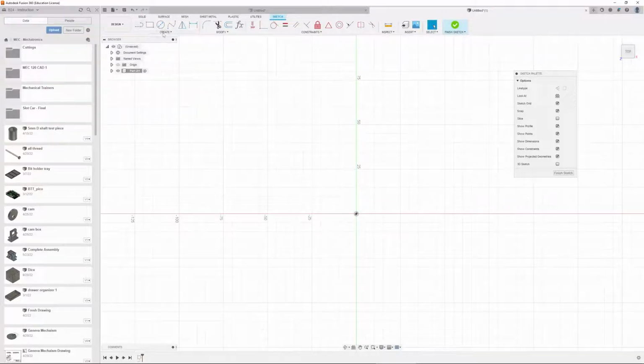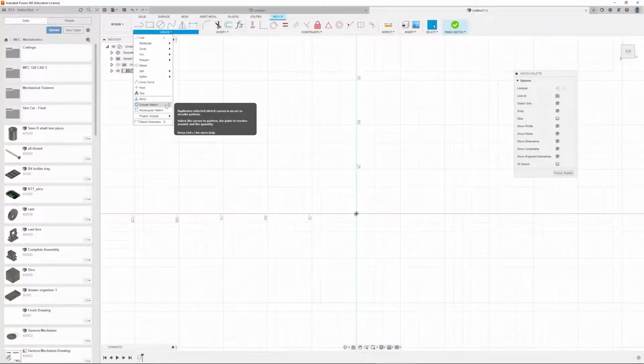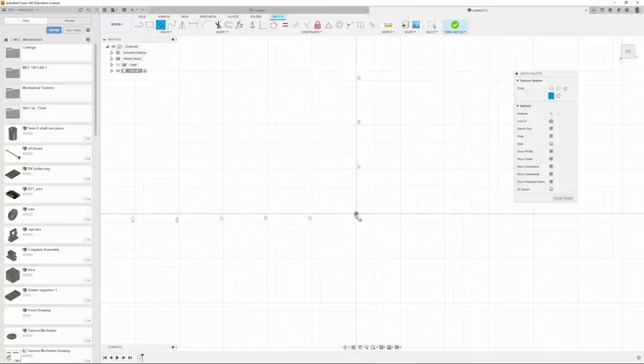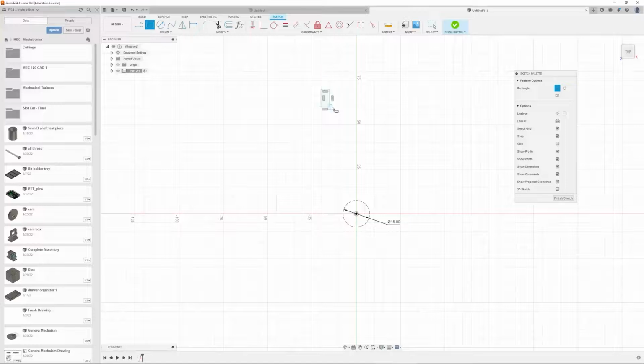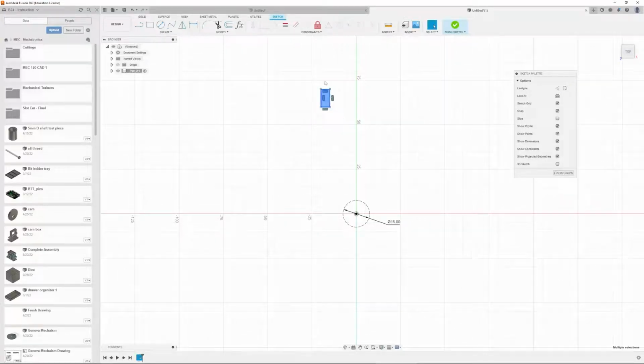The next pattern tool that I'm going to demonstrate is the circular pattern. This tool can be used in a variety of ways. I am going to, again, create some construction geometry. Oh, 2 is probably a little small, so for the sake of visual communication here, I'm going to make this about 15. And then I am going to create a number of rectangles in a circular pattern.